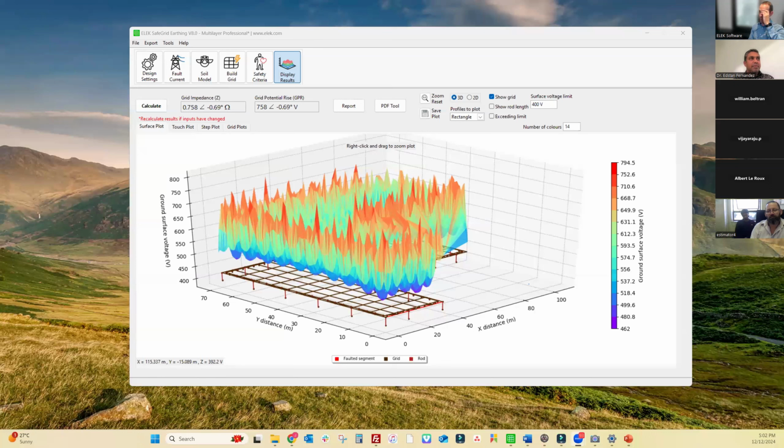Well, we model the cable, but in a simple way, we model the conductor and the screen, or the earth return. So usually it's the screen of the cable or the armor of the cable or the sheath of the cable. So we need to model the conductor and the sheath or the screen or armor in its dimensions, so its diameter and its series resistance.